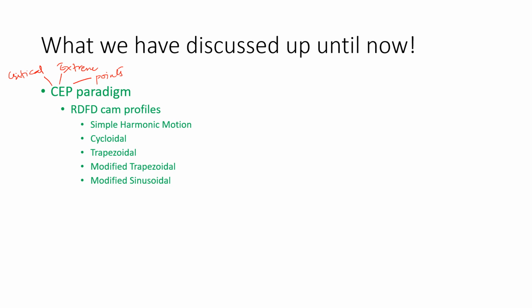And in order to explore it, we selected one big class of cam profiles, which are called RDFD, which corresponds to rise, dwell, fall, and dwell. So there are going to be two parts where motion is happening, in rise and fall, and in between these two, you're going to have phases where there is no motion, called dwells.